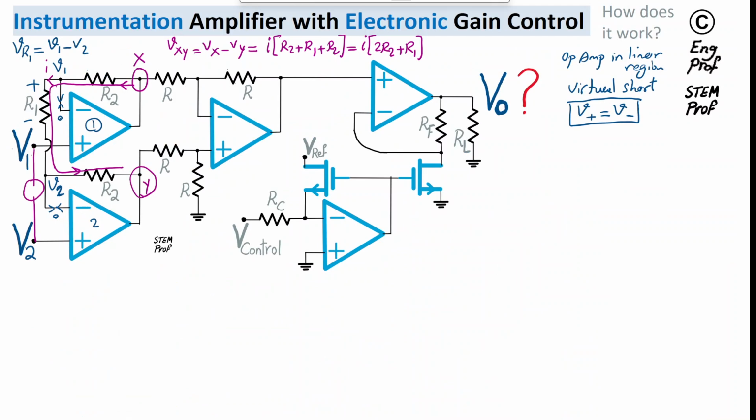Now we computed Vxy. Let's refer to this as equation number 1. What we now have is the voltage drop across these two nodes, Vx and Vy. Let's still refer to these two nodes as Vx, the voltage of node X, and the voltage of node Y. These are the two inputs to a difference or differential amplifier shown here, that with proper selection and with properly matched resistors R, the 4 resistors shown here, should purely compute the delta between these two.